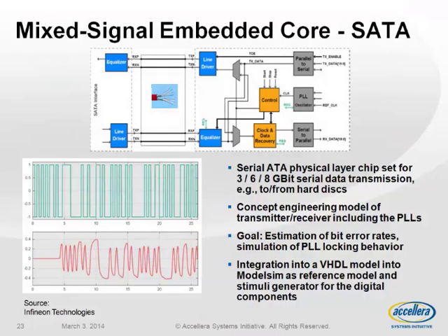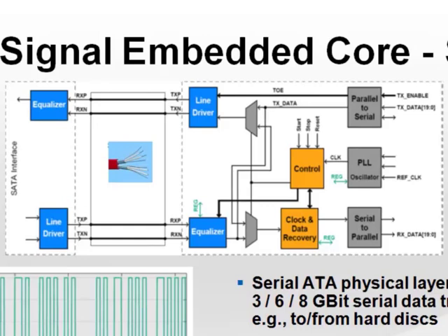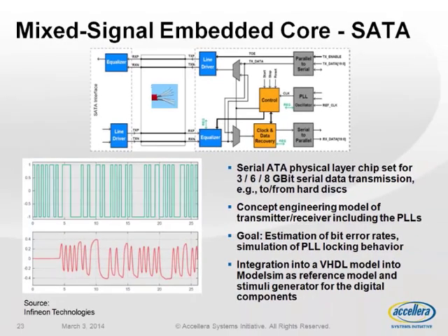Then there's another application area for high-speed interfaces. If you want to design especially the equalizer algorithms, then you need a model. The model at one hand at the line, at the driver circuit, to understand the analog behavior. The transmission, of course, is digital, but if you look at what happens at the line, then you see there is analog behavior, and you need some fast model to develop the algorithms to equalize a digital behavior.